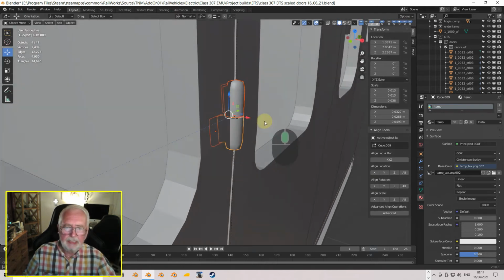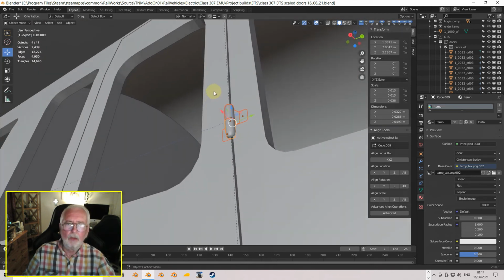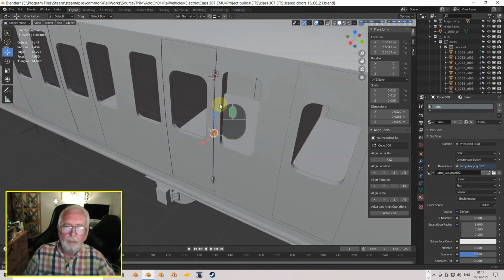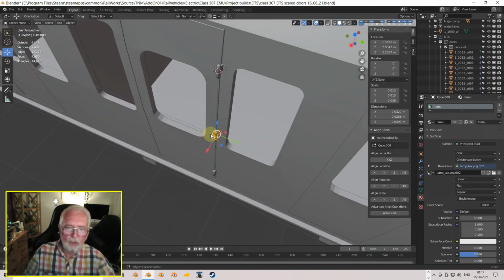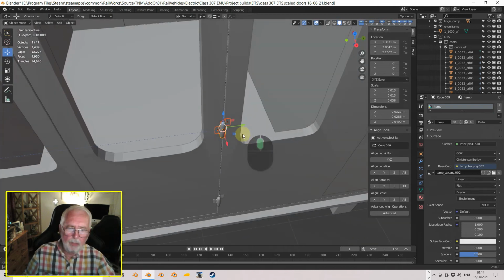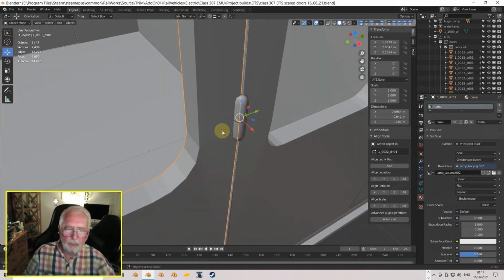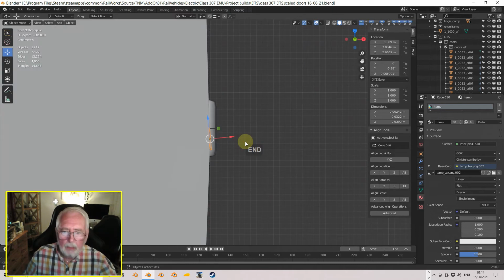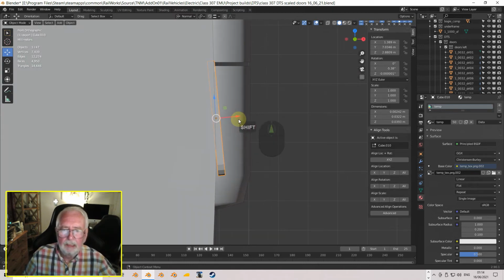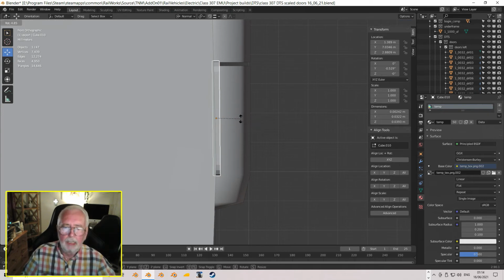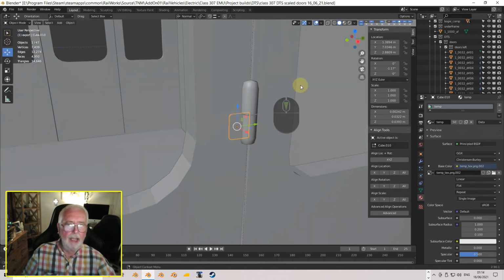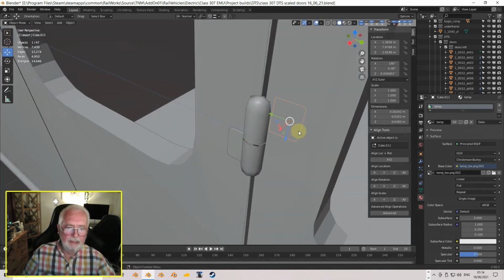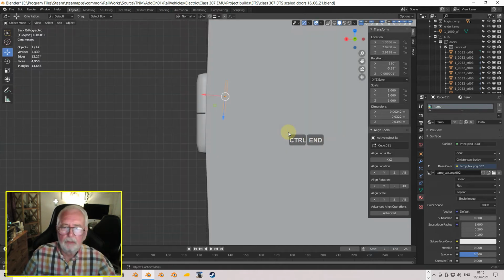Now you'll see that because of that standoff top and bottom, the center is right against the edge, so that's fine, that'll be okay. But what we will need to do is move this plate. Okay, so bring this plate forward. Okay, go end on, because you'll have to rotate it. Yeah, so rotate that. Now make it parallel. Let's hold the shift down. Yeah, that's probably round about it. Yeah, that's okay. And same here, we can select that plate, and let's go to the front view.